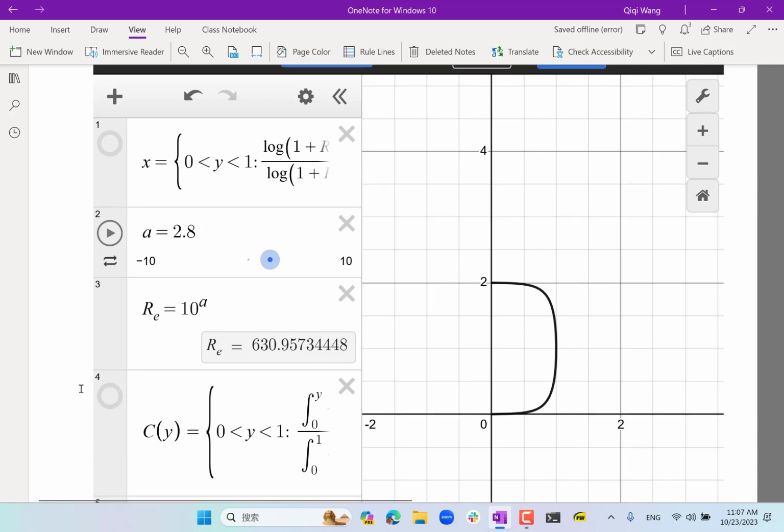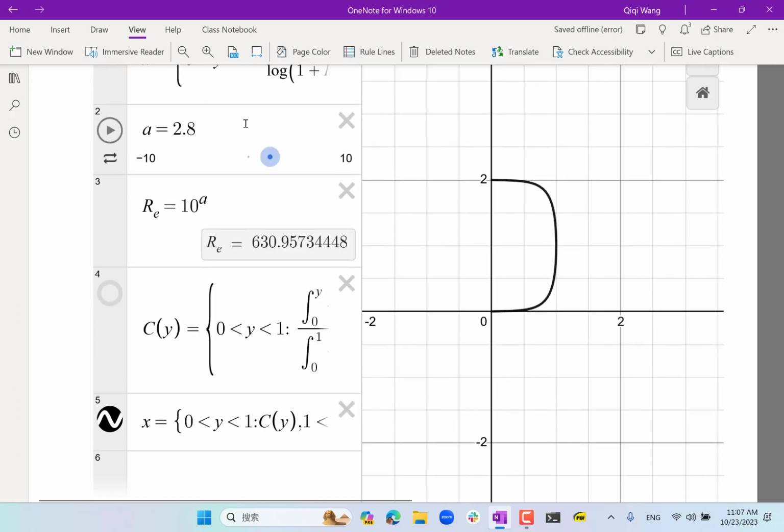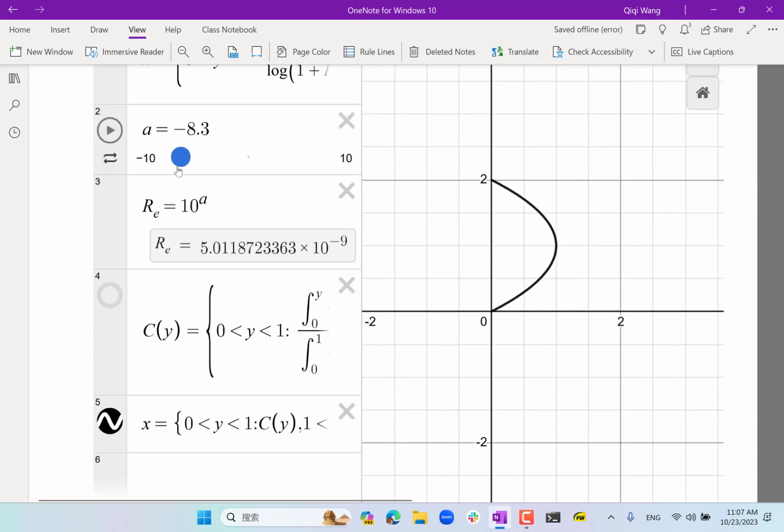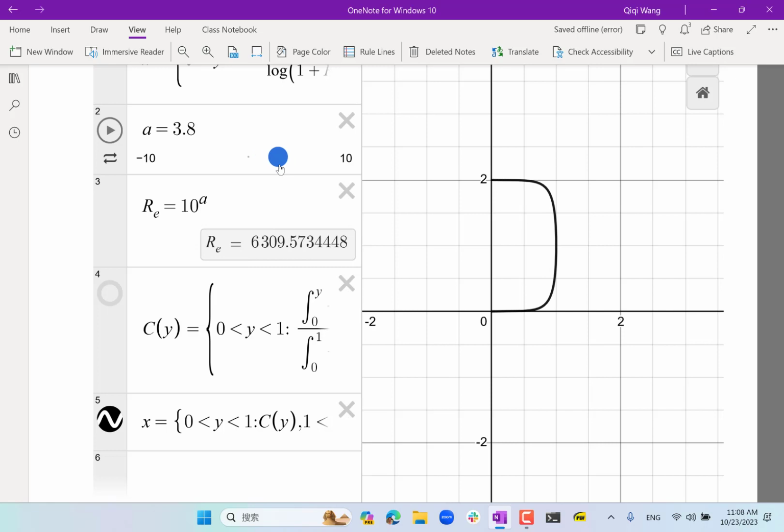And we reached a similar conclusion in the sense that when the flow is laminar, the profile is parabolic, and when the flow has more and more turbulence, there is less and less velocity gradient in the middle of the channel, and more velocity gradient near the wall, right? Or the vorticity in this case is more concentrated closer to the wall, and less in the middle of the channel. It's going to be the same for turbulent boundary layers.